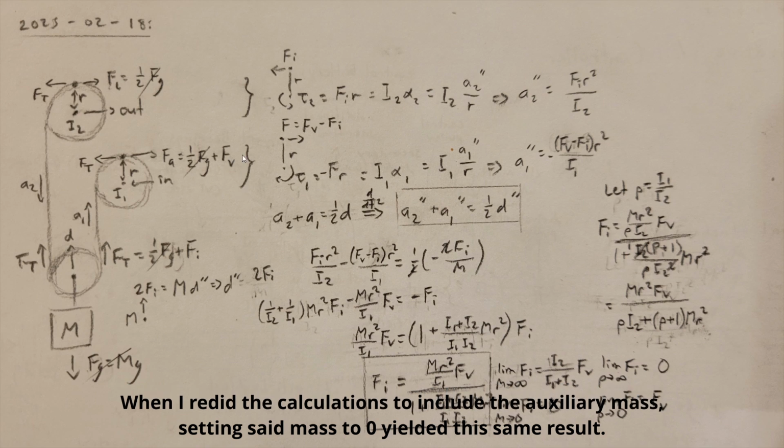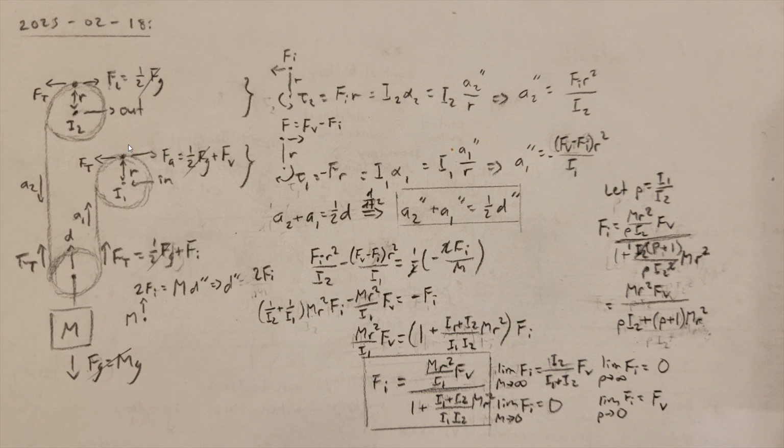Fv represents the varying force applied at the input. This causes a torque, and hence a rotational acceleration on the input sprocket and a tension on the chain. That tension pulls the Huygens weight upward and applies a torque accelerating the output sprocket. Due to mechanical advantage, the sum of the downward movement of the left side of the chain and the upward movement of the right side of the chain equals half of the upward movement of the Huygens weight, as shown by this equation. Knowing this, we can solve the equations to yield the force Fi acting on the output in terms of the force Fv applied at the input.